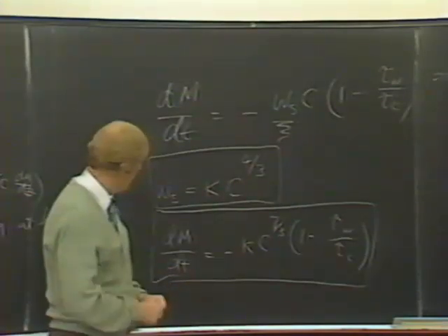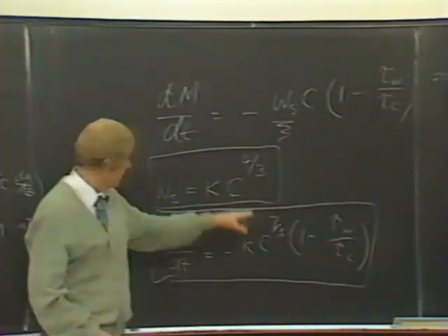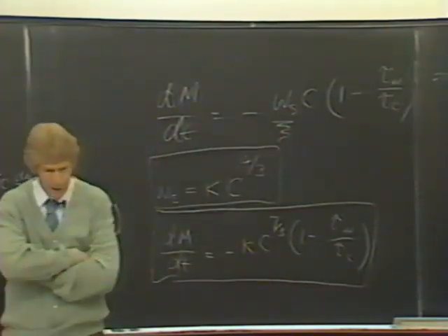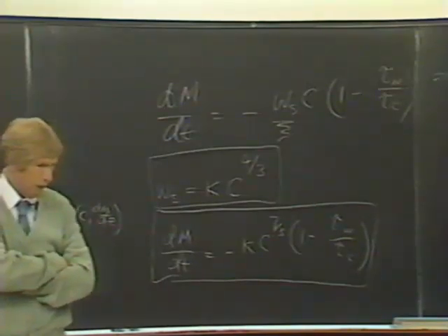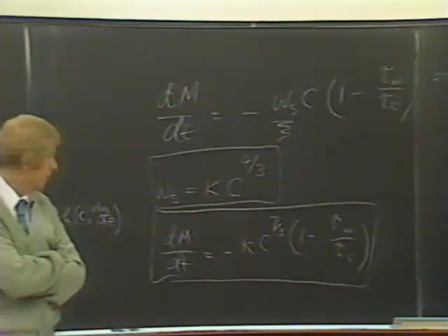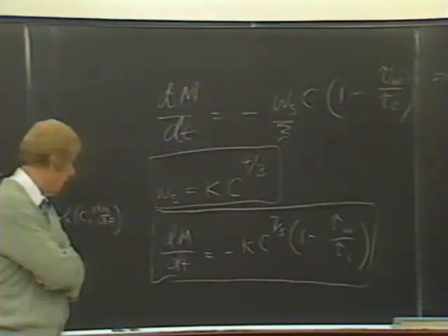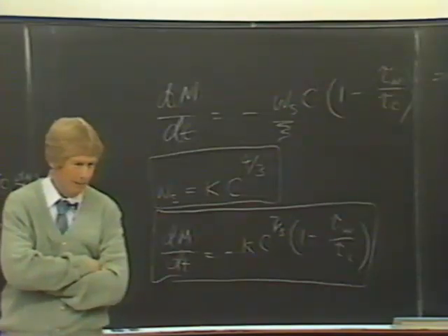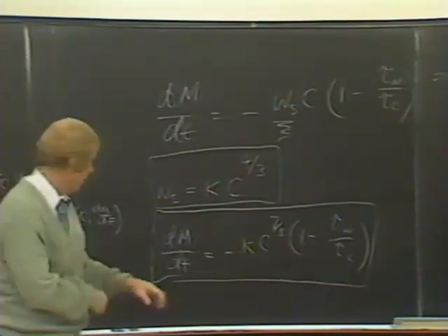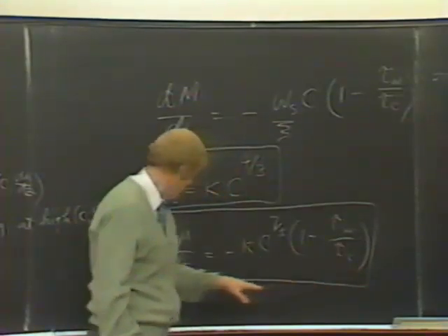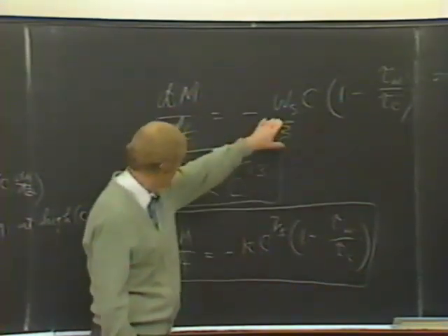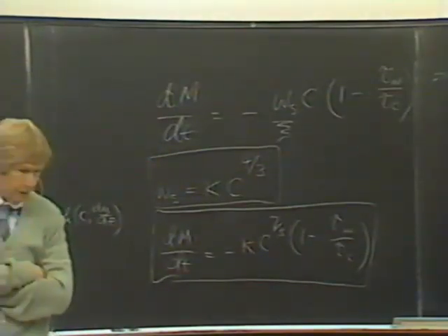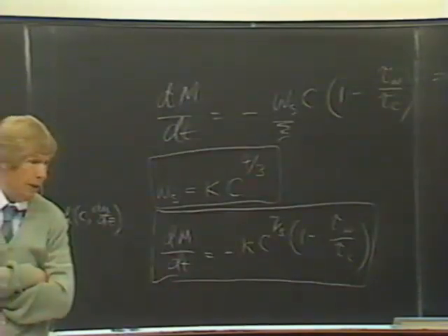You can do that either by having sampling ports along its length and measuring the concentration, or one sampling port and measuring the concentration as a function of time. Then you can get the settling velocities and use that. That's had mixed success. This is called an Owen tube, after Michael Owen, a worker at the Wallingford Hydraulics Research Station in England.